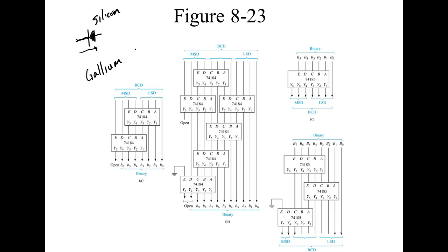What these things do is they only let current flow in one direction, so you have to bias them correctly. If you don't, they won't glow at all. But if you bias them, then they'll glow. They'll actually produce light, and they produce these colors. What we normally do is encase these things in the color that they produce to make them more vibrant. So normally a red LED, light emitting diode, will be in a transparent red lens, right? You understand?